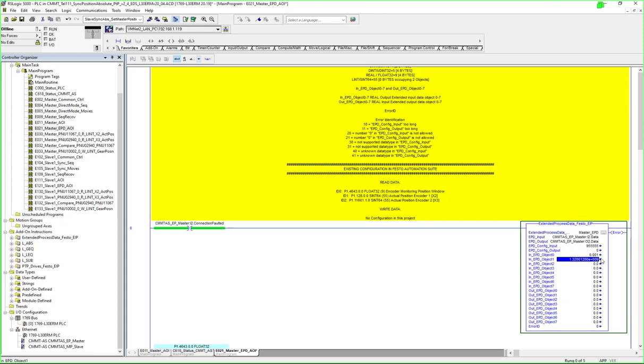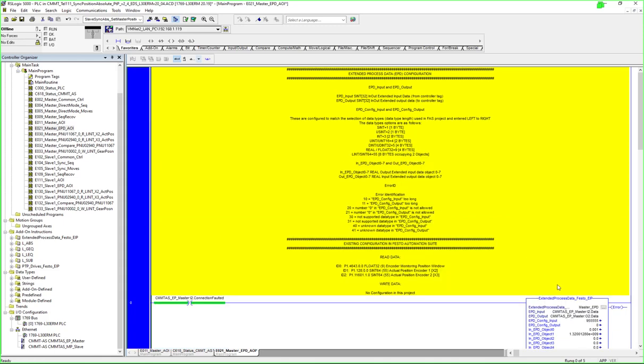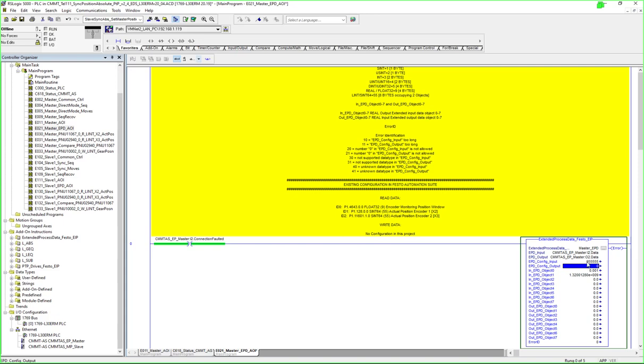So in some circumstances, I use the add-on instruction, for example, this floating point coming through, and for other ones I simply take the raw data and do my own conversions, because all this add-on instruction does is convert the raw data into these objects here, and then the user can use the objects throughout the code.